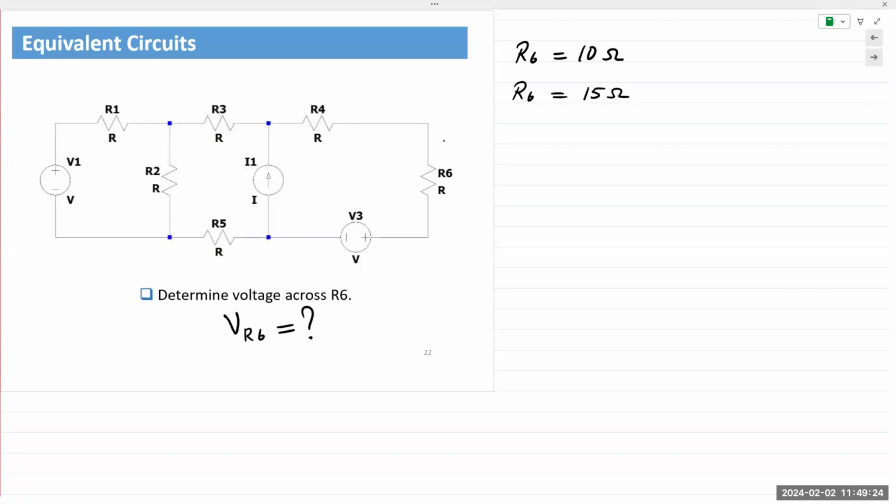He postulated a theory, this was in the late 1800s. He said that if you wish to analyze a circuit like this, if you wish to find a particular value for a component, what you could do is remove that component from the analysis, analyze the rest of the circuit independently, and represent that entire circuit as a voltage source in series with a resistor.